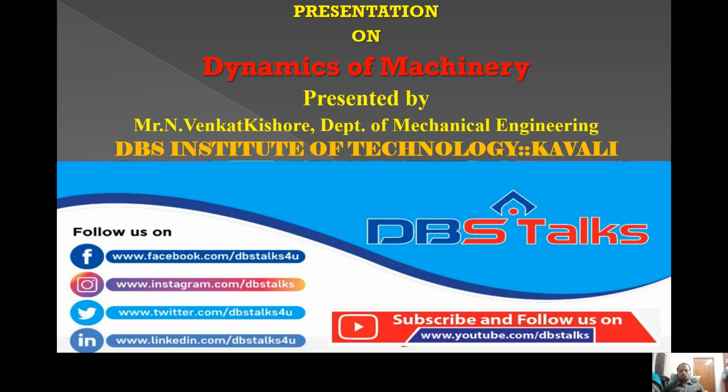MBD, that is one more triangle. So if you see these two triangles, sine by cos is tan. So IM by BM is equal to tan alpha, and at the same time MD by BM we will call it tan beta. So substitute these two terms in the equation, we get Fc is equal to mg tan alpha plus capital Mg by 2 into tan alpha plus tan beta.